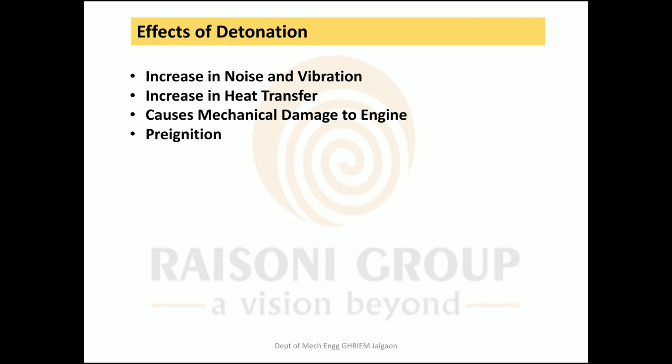The hot gases greatly increase the amount of heat picked up by the spark plug. Overheating of the spark plug may be to such an extent that the plug electrodes may become incandescent and ignite the fresh charge long before the ignition is supposed to occur. Thus, overheating of the spark plug electrodes due to the effects of detonation can lead to pre-ignition.